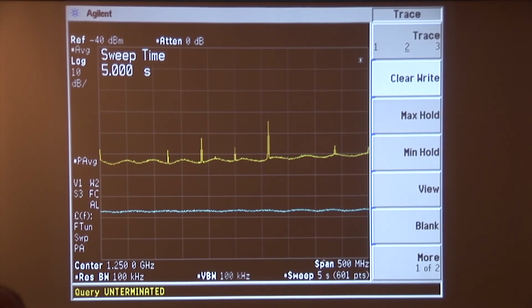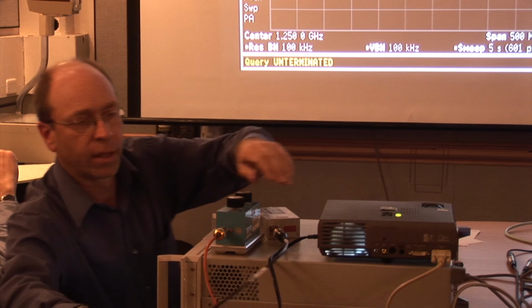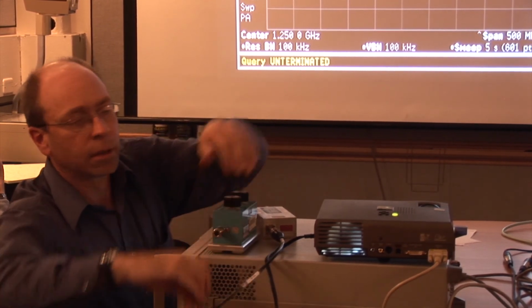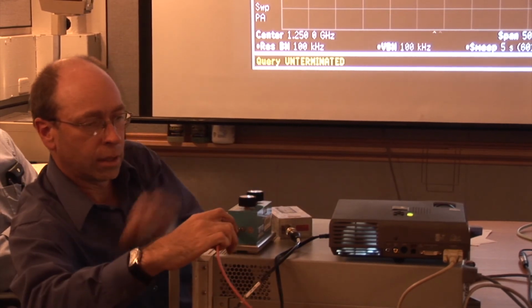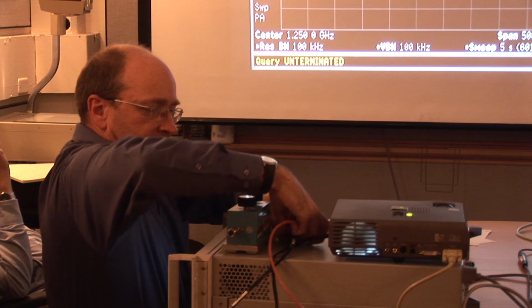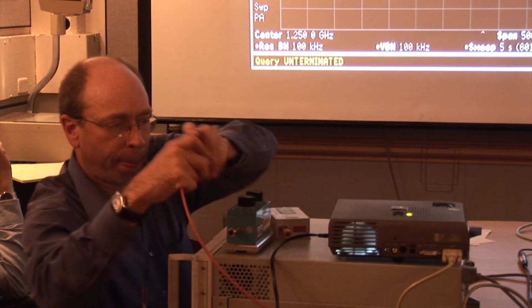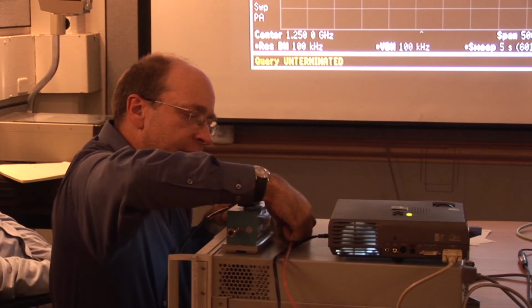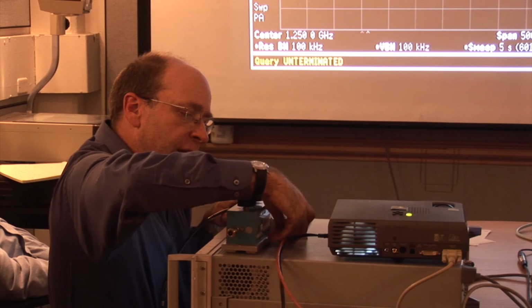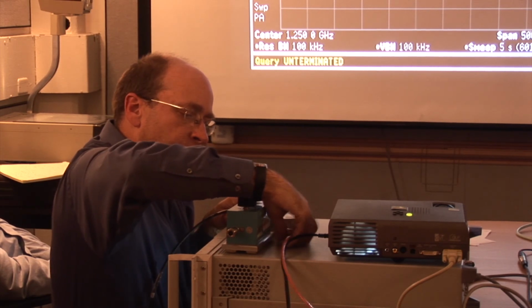Now, I'm going to demonstrate how if we insert attenuation after the output of the amplifier. I have to do a very quick rewire here. See, we'll bring this in here. No, sorry, bring this in here. There we go. What I'm going to do is put the step attenuator between the amplifier and the spectrum analyzer so that we can actually demonstrate how we can reduce the gain and have a negligible impact on noise figure to a point and optimize now the overall behavior, the overall performance of our measurement system.